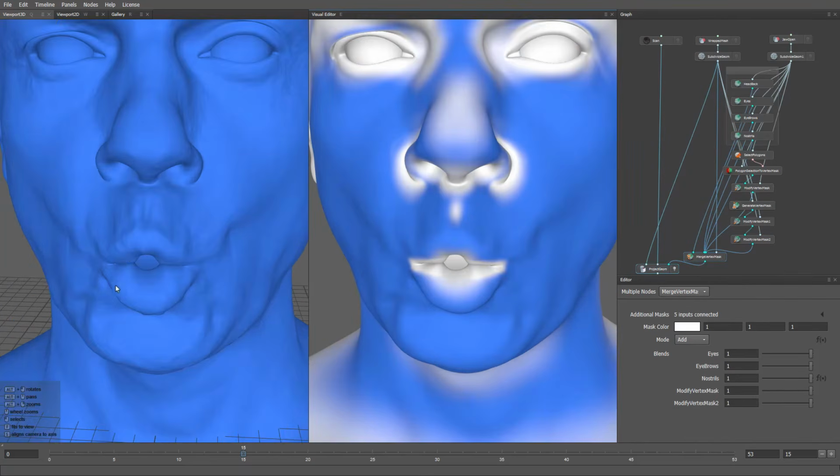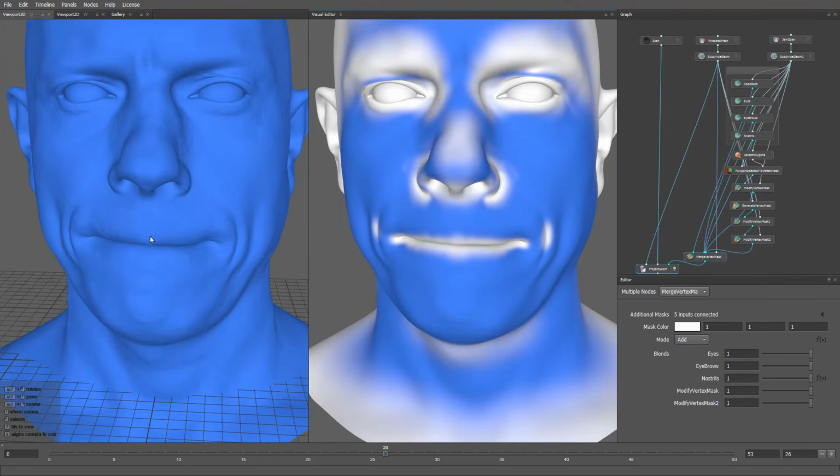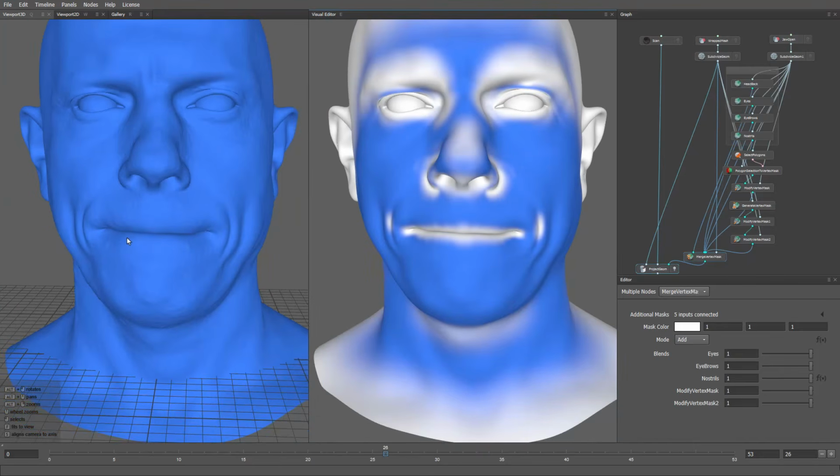We automatically create a mask constraint to prevent projecting onto problematic areas. Disable the mask and compare before and after. Our procedural mask eliminates manual projection cleanup. Let's test this approach on the curled lips expression. Notice the mask expands, making curled lips look correct. The mask also excludes pore projections and eye folds. The result looks correct, adding significant details to various facial areas.